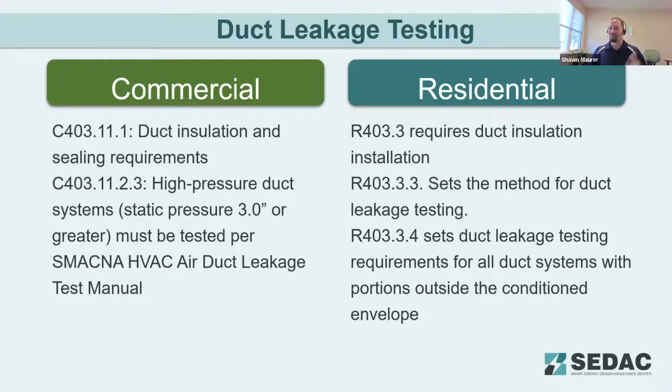For ductwork that's completely inside the conditioned envelope, the 2018 IECC does not require pressure testing for that. So if the HVAC unit and all the ductwork is inside the conditioned envelope of the building, testing is not required. But you do still have to verify that ductwork has been sealed appropriately.